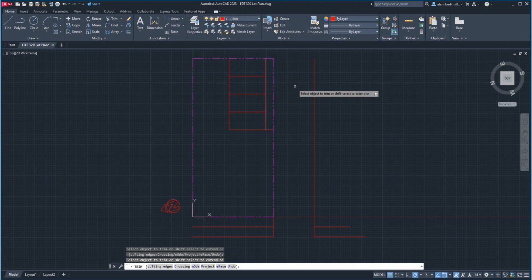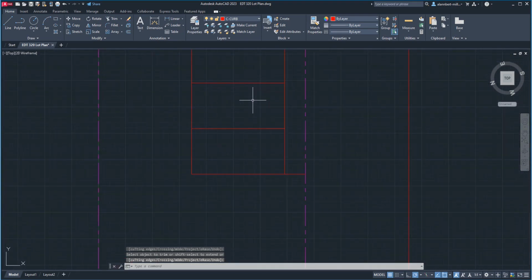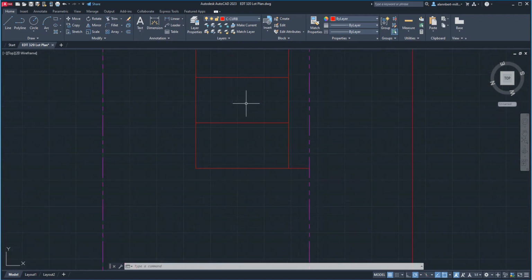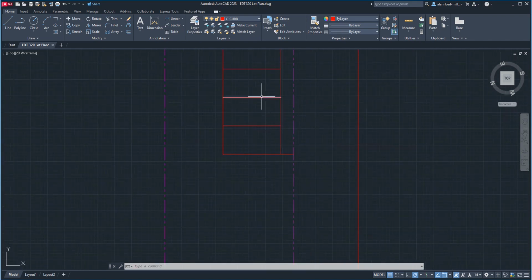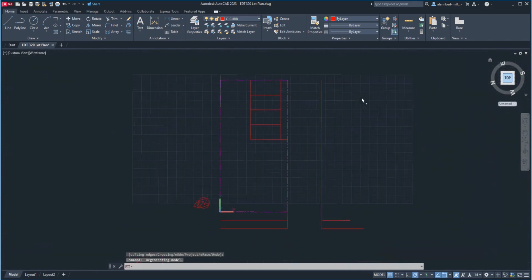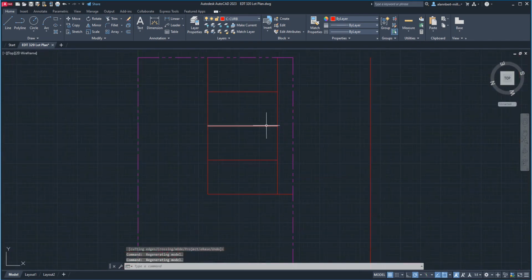And so you want to designate which one is the accessible aisle. Okay, press enter to stop. And let's say you wanted this to be the accessible aisle. You have 2 options. You could either have 5 feet of accessible aisle, but the van accessible must be wider. So in any case, it'll be, I believe, minimum 16 feet, but because we're only doing a 9 foot parking, we're gonna make it standard.